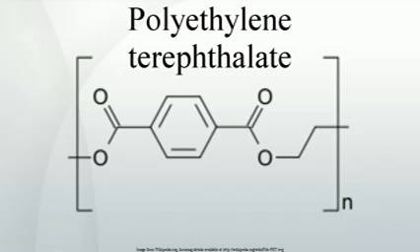Reactive polyester OH or COOH end groups are transformed into dead or non-reactive end groups, for example formation of vinyl ester end groups through dehydration or decarboxylation of terephthalic acid, or reaction of the OH or COOH end groups with monofunctional degradation products like monocarboxylic acids or alcohols. Results are decreased reactivity during repolycondensation or re-SSP and broadening of the molecular weight distribution.